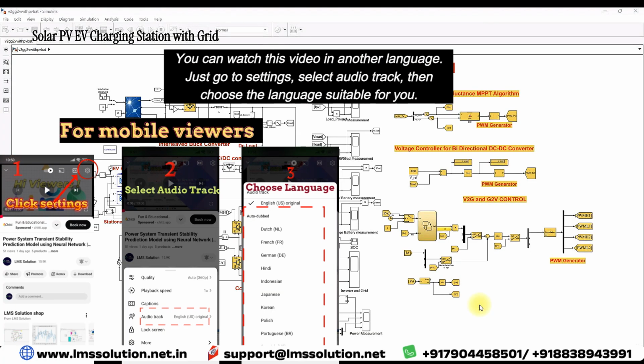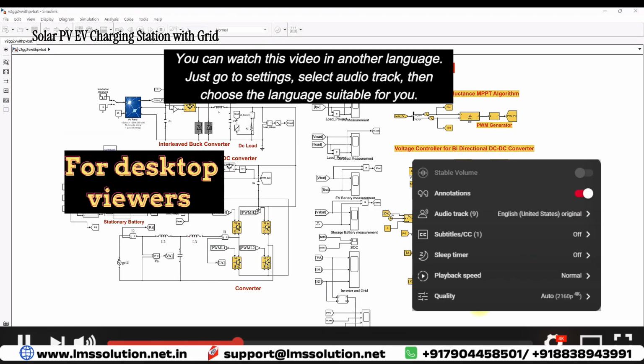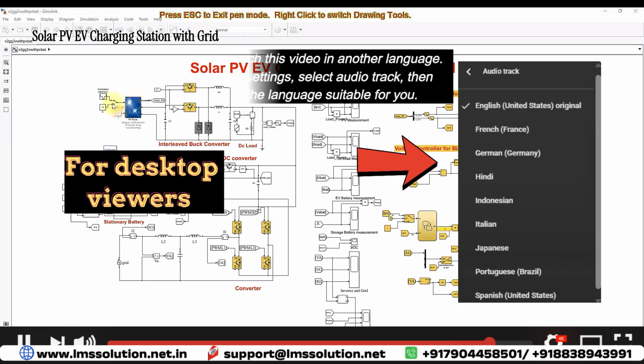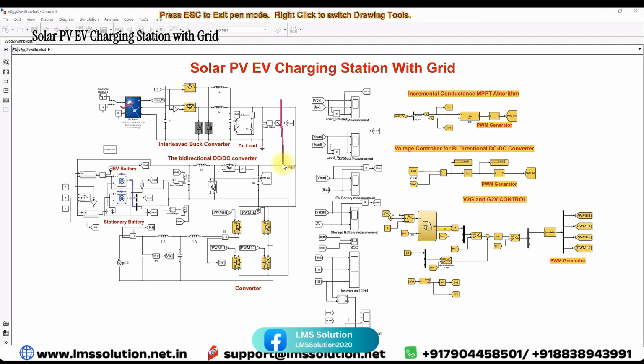Today we are going to see about a solar PV EV charging station with grid integration in MATLAB. This is a simulation model we developed for a solar PV EV charging station with grid integration. This model consists of a solar PV array, and the solar PV array is connected to the DC bus via this interleaved buck converter.